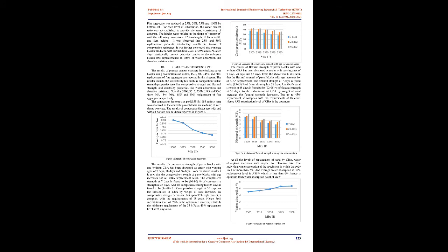The blocks were molded in the shape of unipaver with the following dimensions: 22.5 cm length, 12.0 cm width, and 8 cm height. It was observed that 25% and 50% replacement presents satisfactory results in terms of compression resistance. It was further concluded that concrete blocks produced with substitution levels of 25% and 50% at 28 days statistically present behavior similar to the reference blocks, 0% replacement, in terms of water absorption and abrasion resistance test.